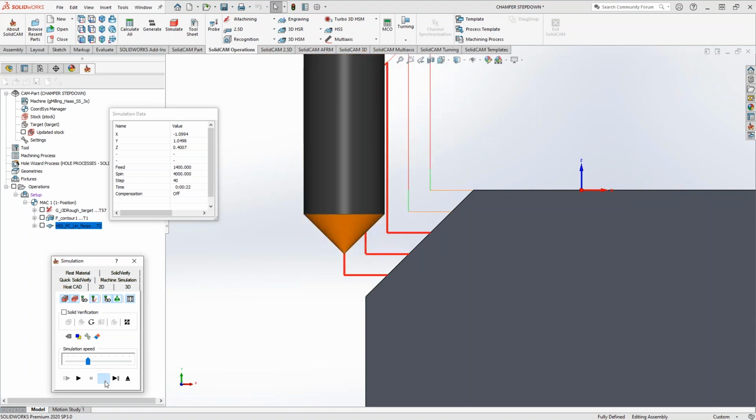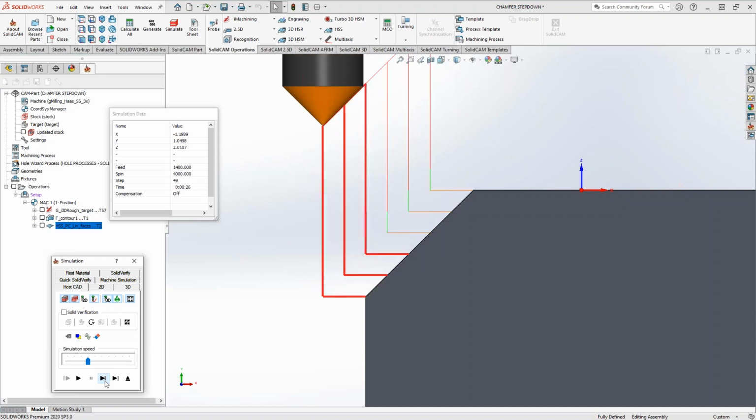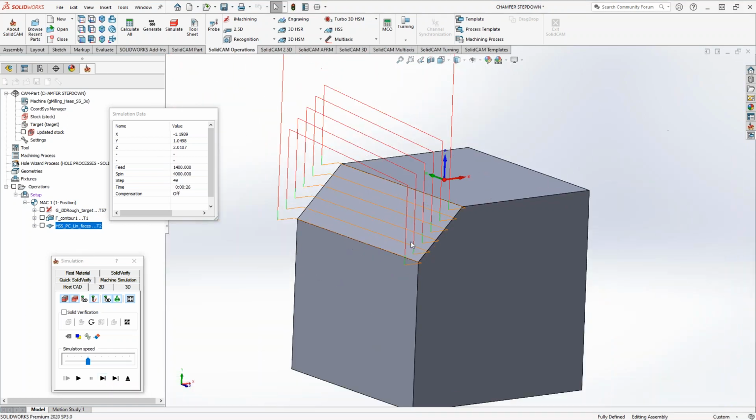If I go all the way to the end, the surface is clean. Between those two toolpaths, you have options to do this sort of thing. A smaller chamfering tool, but on a large chamfer surface. Now, chances are, if you have this sort of situation, you might not even bother using a taper mill or a chamfer mill. You might even try using a large diameter ball mill and then just doing multiple cuts to get a better finish.